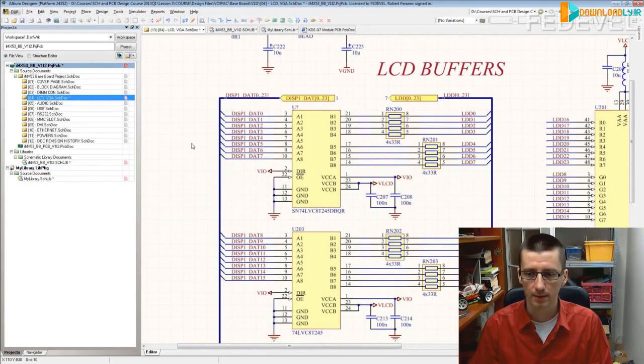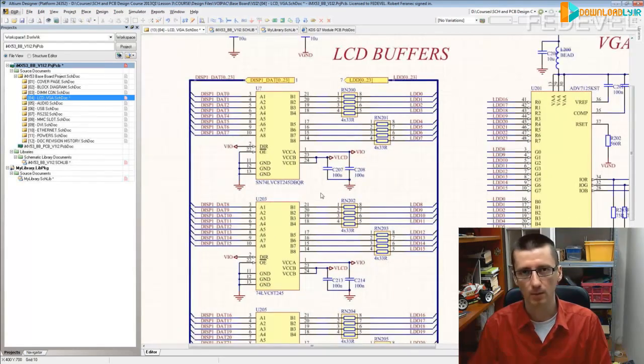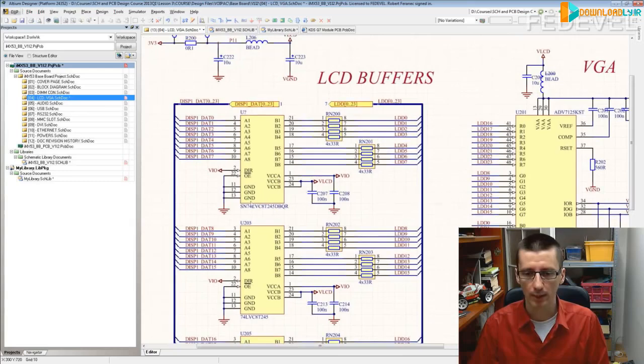A few more tips. You probably use it this way anyway, but I saw a lot of schematics where they just don't do it. Place the components close to the pin where they should be, because when you do the layout, you know where to place the component. Also, when you create a schematic symbol yourself, find some kind of logic.